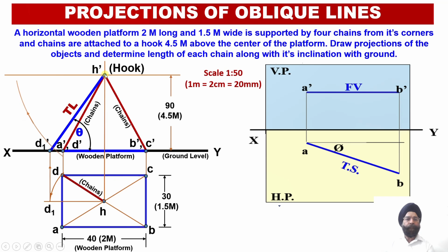We will have our needle point as h dash, open compass equal to the distance h dash d dash or h dash a dash, and then keeping our compass needle over here, open compass up to this radius, draw an arc and extend this arc till it meets the horizontal locus line which is emerging through the point of the needle point, that is h dash. So wherever this curve intersects with the horizontal locus line which is emerging from the needle point, we obtain the points a2 dash and d2 dash.